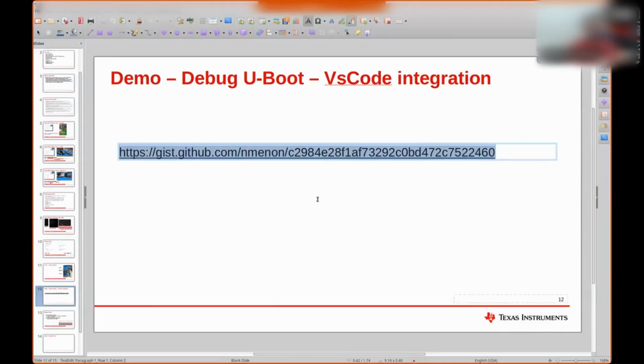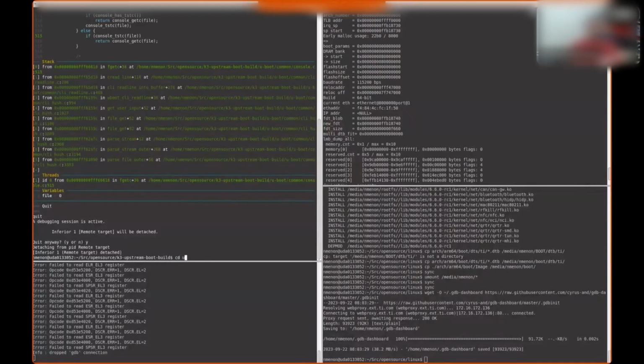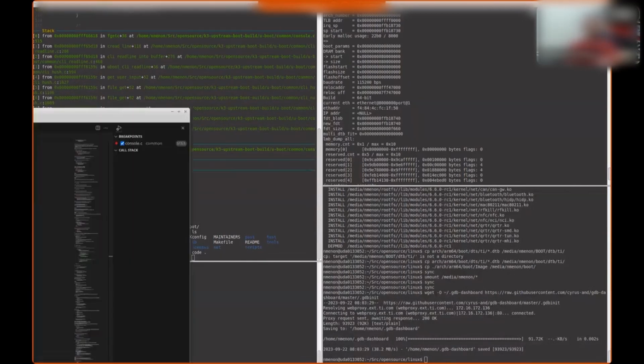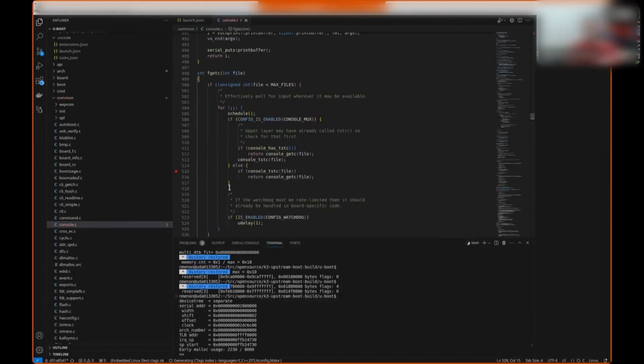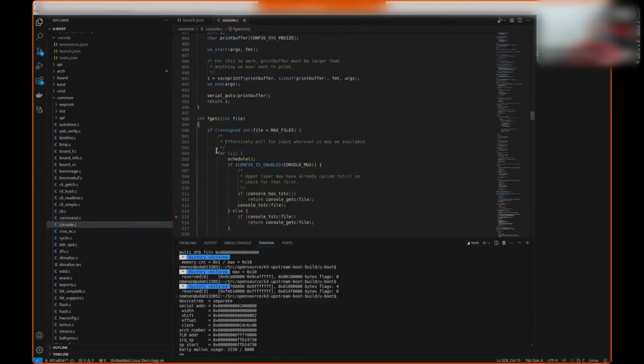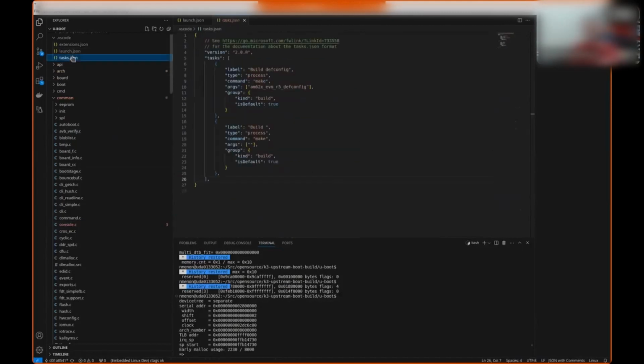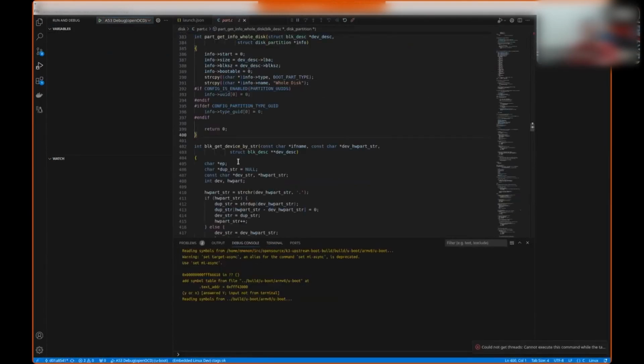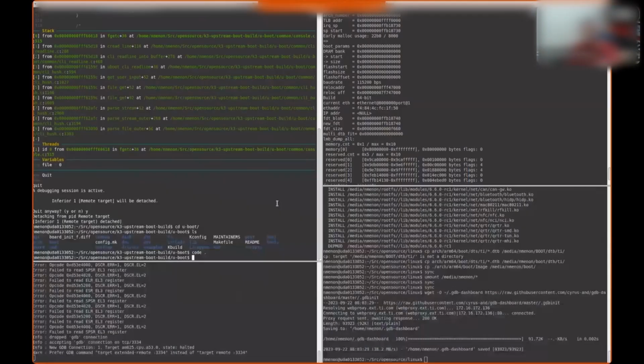I have done this, and this link is already available within the PowerPoint. So go to U-Boot, code dot. All right, my friend, come back here. It shows automatically. It gives you the VS Code option for tasks, JSON, etc. If you pick the debug and select A53 debug, which is what my task list provides, it'll automatically attach and load it up here. I had to give the text address difference, which I did not put in.